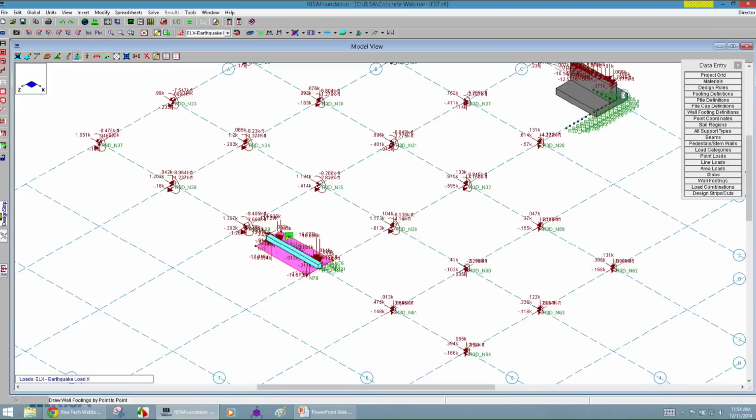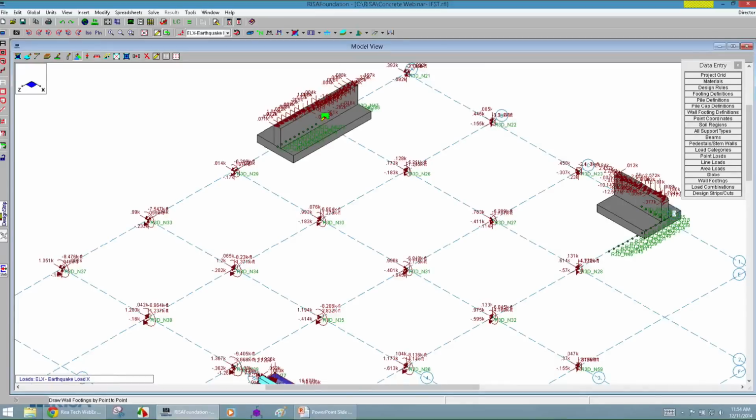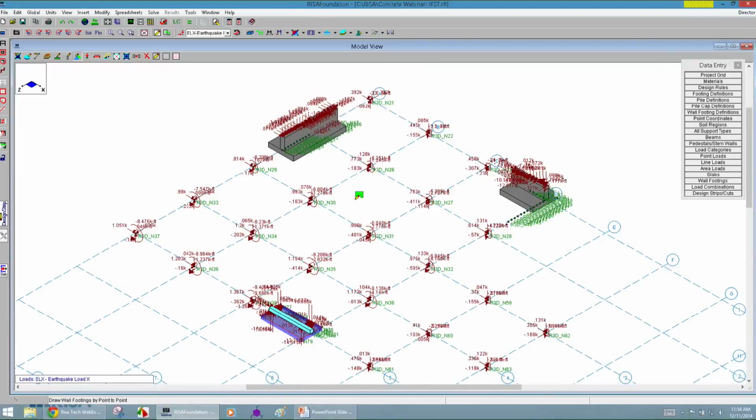So this is going to be really just a slab. So it's a slab with a footing on top of it, or a stem wall on top of it. And you can adjust that. You can redraw that slab. So you can actually do kind of any shape you wanted with this. Now, this one is going to be more of a set element. So this type of element gives us a report on it, which is really helpful. And it allows us to see some information on just that stem wall and that strip footing there too.